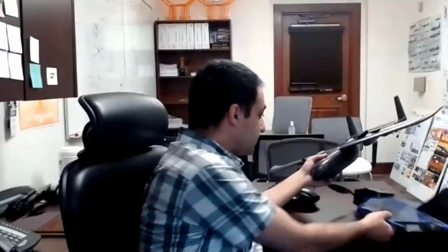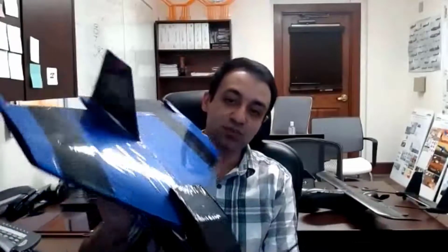And it can also glide. It's like a glider, which has a higher aspect ratio wing shape, so they can actually do gliding. So this is a comparison between these wing shapes. This drone has the lowest aspect ratio. It means it would fly at a lower range compared to this larger wingspan drone with a higher aspect ratio, and it would also fly with lower endurance because it has a lower aspect ratio.